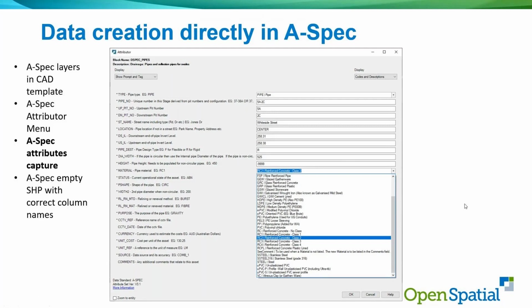We've had a very good example recently where we're working with an existing A-SPEC member that has been accepting data, and we took one of their ones that was accepted and picked up that, for example, on D-Spec, the pipe material, concrete, didn't exist in the lookup table. You needed to subdivide the concrete into one of the other categories. So part of the process is actually doing the validation, which is an important part of the process.